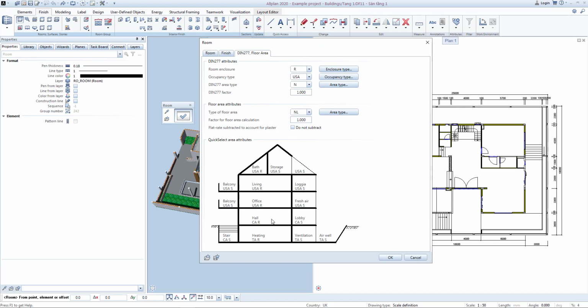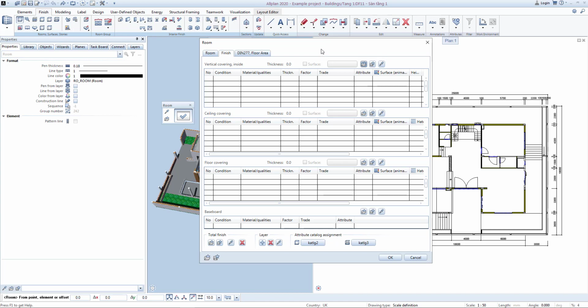Two, Finish tab. You will define the size as well as the finishing material to calculate the room volume correctly. Vertical coatings such as tiles, paints or soundproof coatings. Specifically, it will include the definition of name, thickness, material, surface, height, depending on the number of layers you delete or add to set.